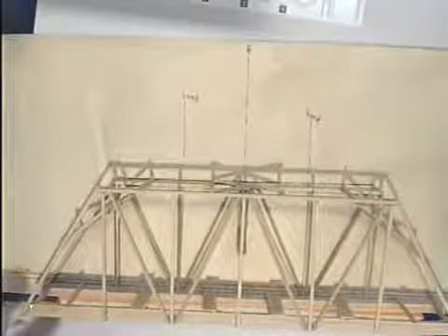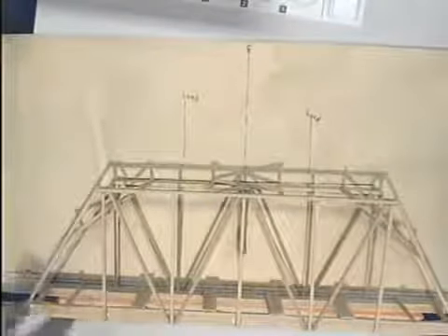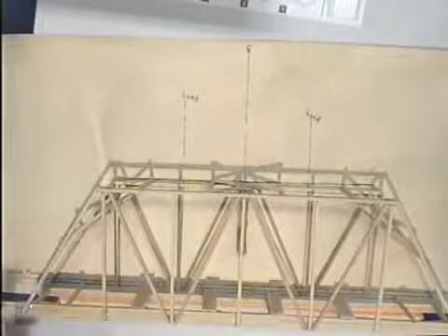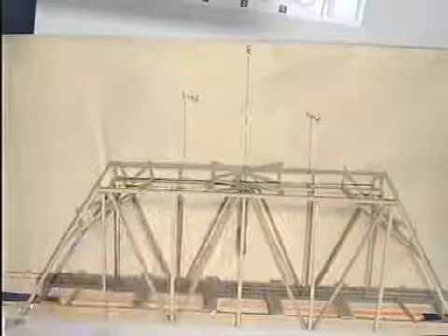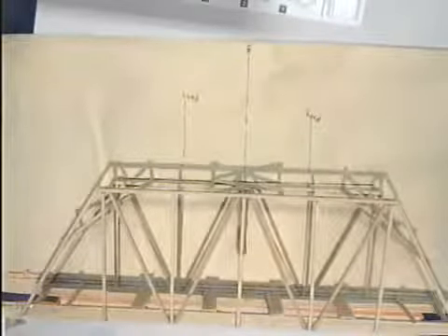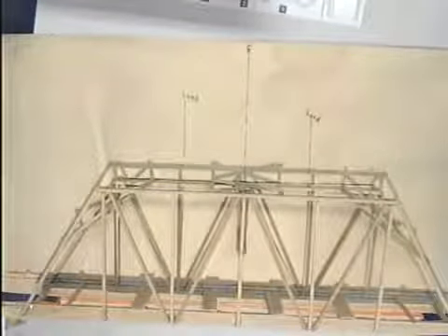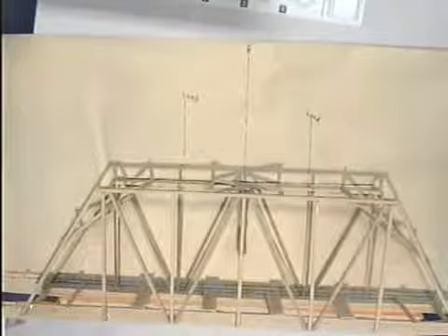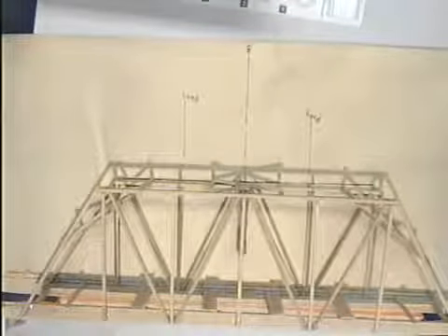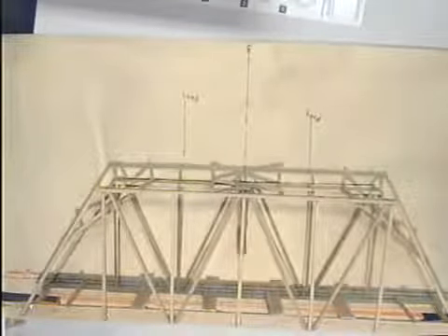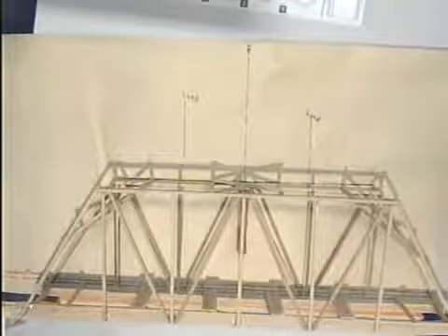If you're doing the efficiency of the bridge, you want to make sure that the bridge is as light as possible. This bridge weighs about 25 grams. It lost about 4 grams of weight. It lost close to 20% of its weight when the glue dried. And it takes overnight for Elmer's glue to dry. So do this ahead of time.